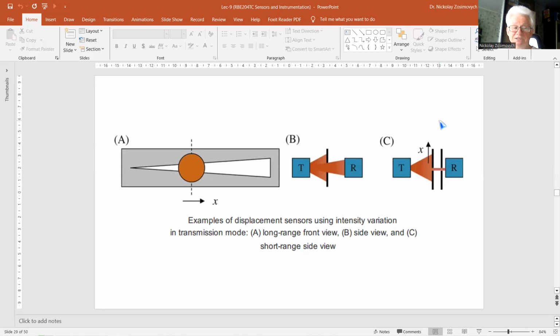By shaping the slot in a particular way, an arbitrary transfer function can be obtained. For instance, a logarithmic or a parabolic relationship between displacement and transmission. For each application, optimal dimensions can easily be found by inspection of the amplitude of the movement by the monitor.